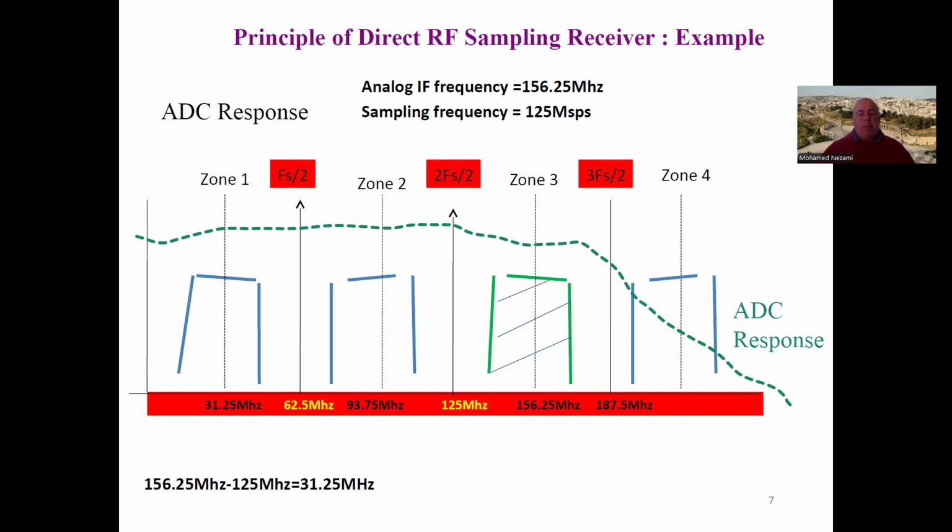That is the digital downconverter, which digitally downconverts the signal to baseband. In previous days it used to be done in the FPGA or in custom ASICs, but now it's really becoming a part of the ADC.